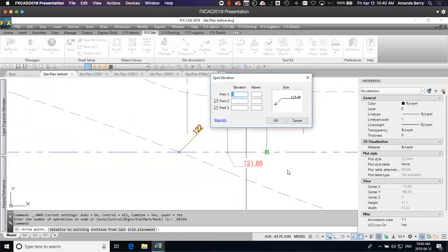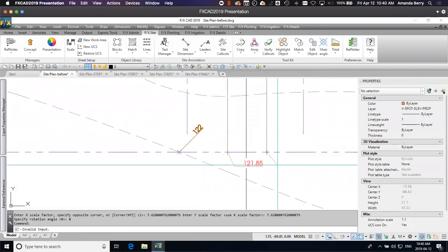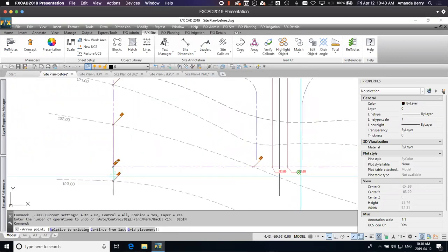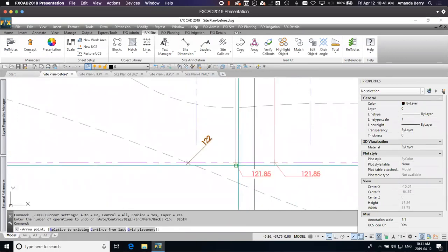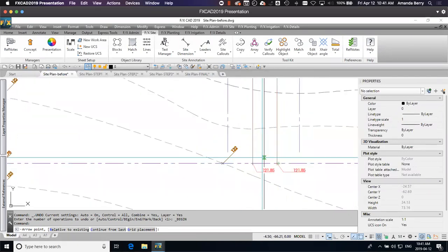And I'm going to communicate that on both sides of my roadway, so it's very clear of what I'm going to do, because what I am going to communicate along here is that I want to crown this roadway. And I want to crown it so that it drains positively, and we learned that for asphalt anything over 1% will drain positively.